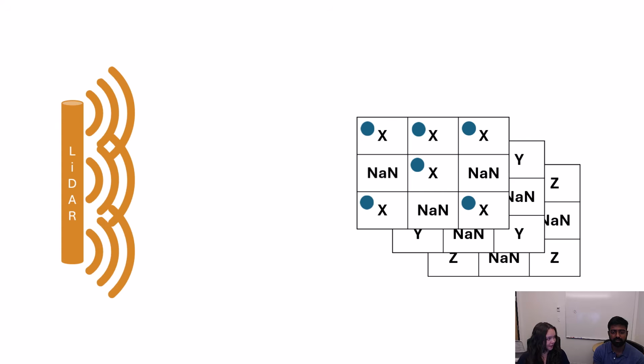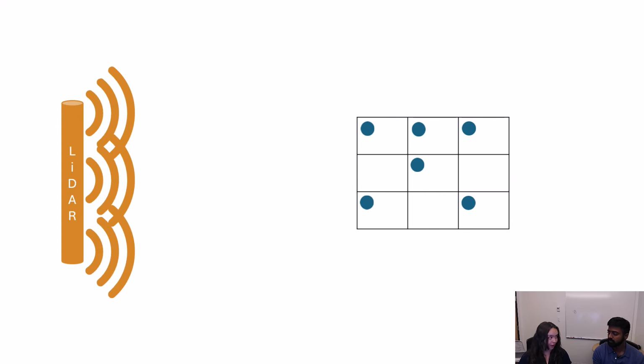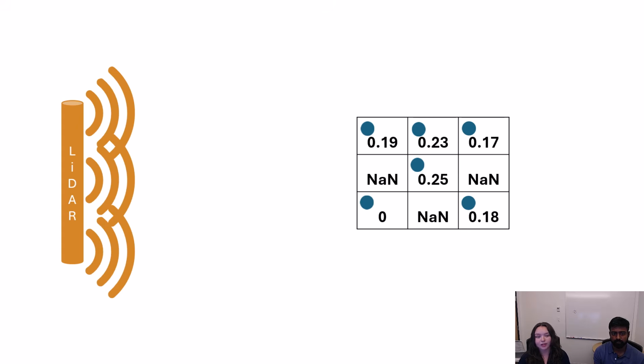That makes sense. In addition to the point cloud data, LiDAR will also collect intensity data, which is just a measure of how reflective each point in the point cloud is, or how much light was returned to the sensor. Different objects and different types of surfaces might be more or less reflective, so this is just some extra data that can be helpful for something like object detection.